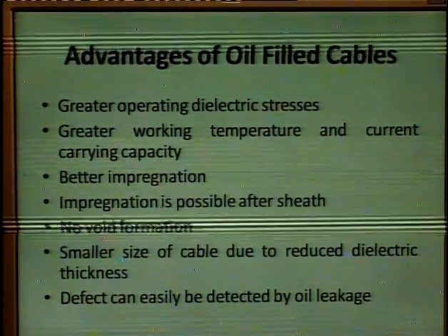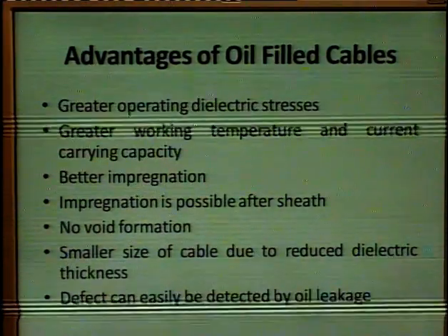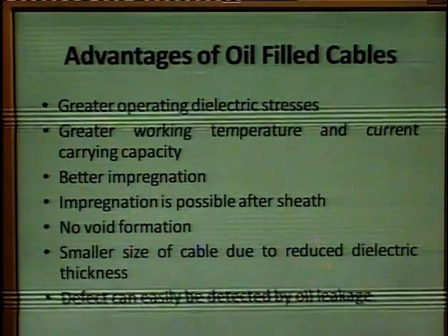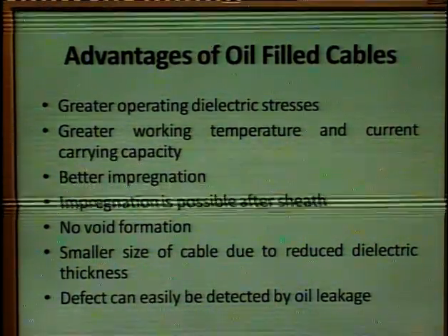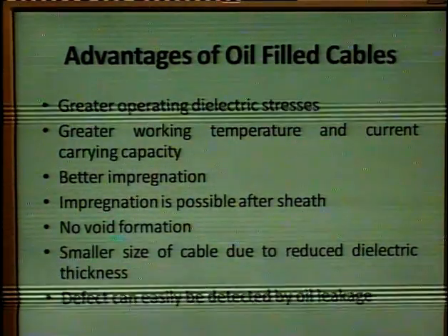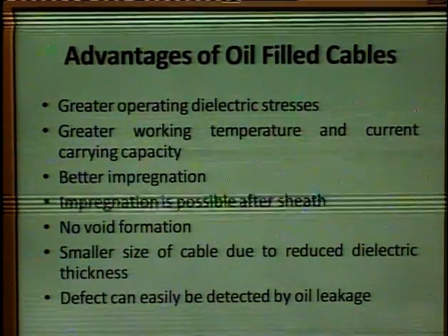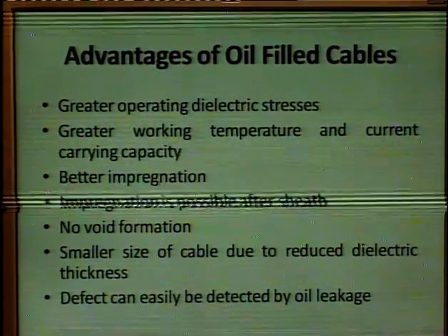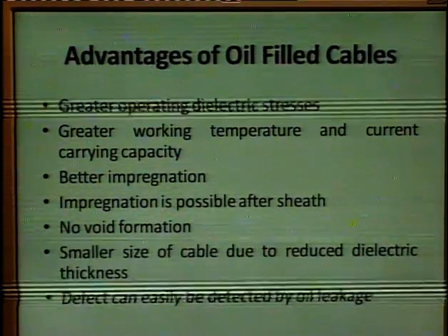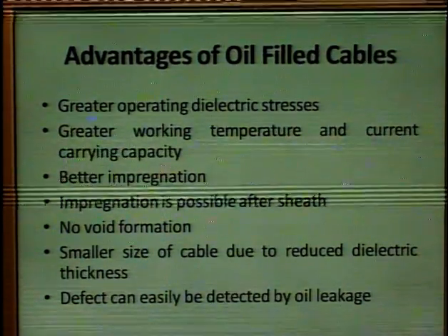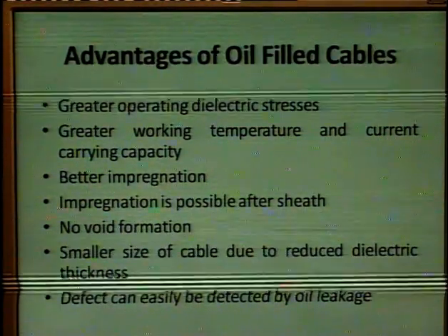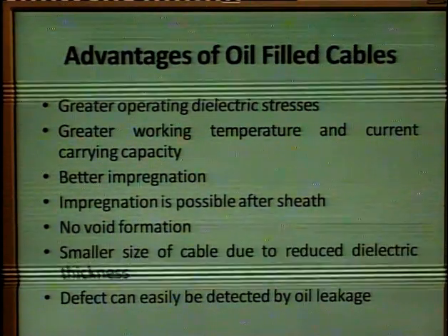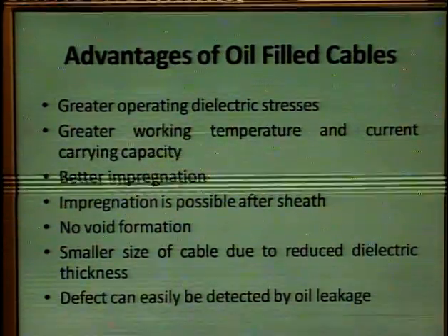Better impregnation, and impregnation is possible after sheathing, no void formation, and the smaller size of cable due to reduced dielectric thickness, and the defect can easily be detected by the oil leakage.